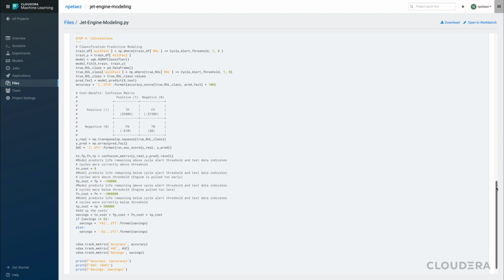With some simple manipulation of the data, we add labels based on how much remaining life the engine should be removed at. In this case, our threshold is 40 flights, which is roughly 1% of the total life of the engine, as engines are typically designed to be overhauled every 4,000 flights or so. With the data labels in, we can now create a classification model.